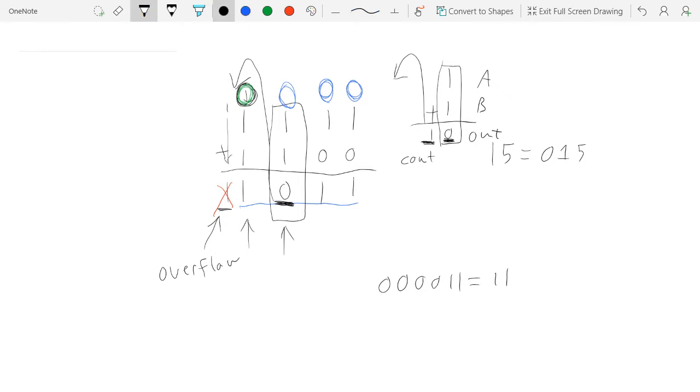So when I say I've got 1 plus 1, and I want to do that in binary, A is 1 and B is 1, and I want to add them together, and I get 2 as the answer, I'm actually carrying in 0. So I've got this number carry in. So I've actually got 3 inputs here. I've got our carry in input, our A input, and our B input. And I've got 2 outputs here. I've got our output answer, and I've got our carry out bit, which gets chained into our next column for the carry in bit for that next column. So this is kind of how we modularize our arithmetic here. We've got 3 inputs and 2 outputs.